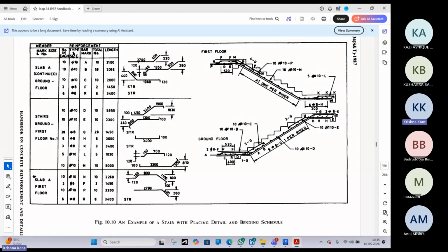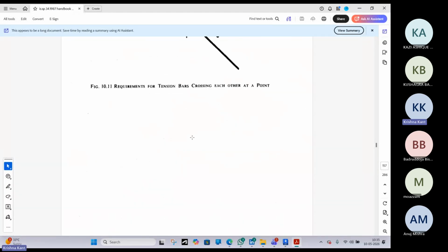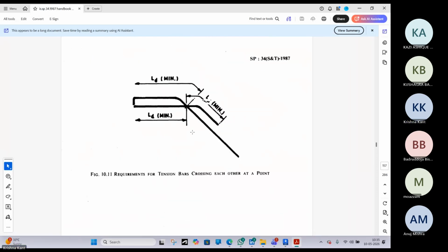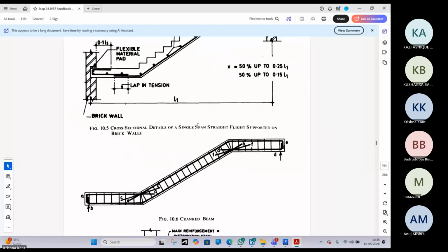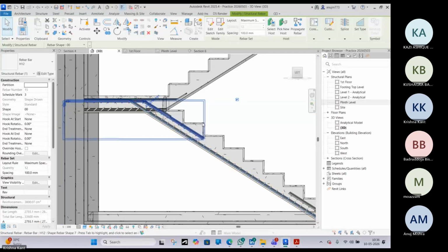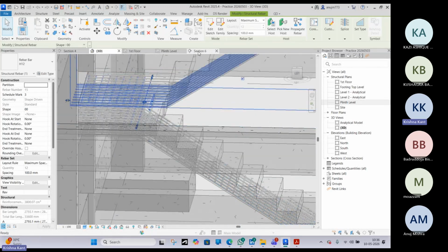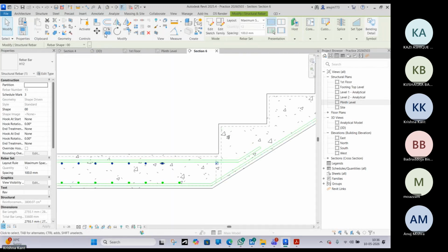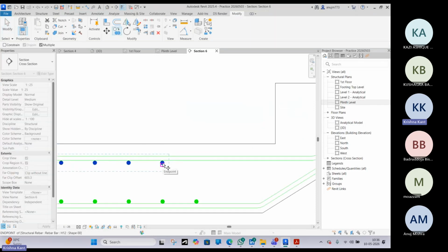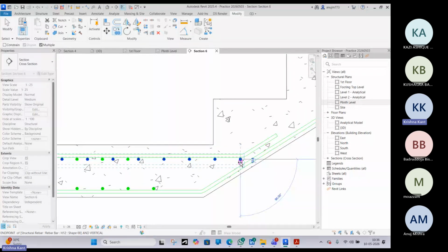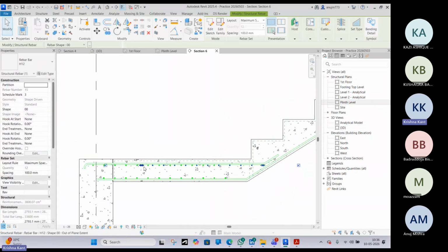Yeah, there is no extended portion of this rebar. Okay. So what we can do, we can copy this section, copy these rebars. This group I am copying, okay? Notice this one. I'm copying this group, pasting it over here, bring it from this end.